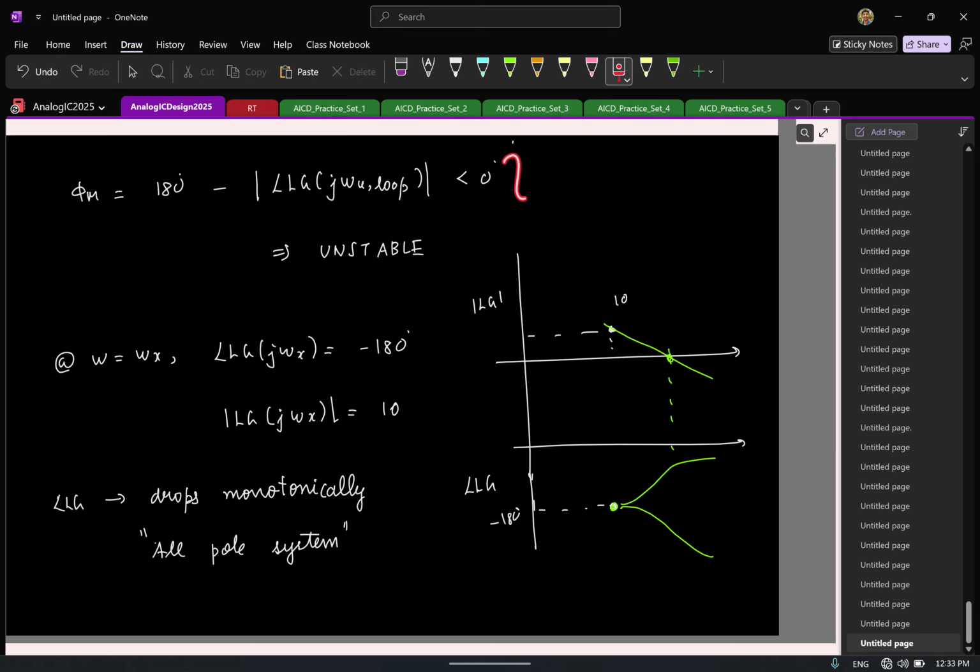So that's why phase margin is a stricter constraint than gain margin, especially if you have LHP zeros. In fact, in practice, there are many systems for which when the phase is minus 180, the gain can be 1000 or 10,000, and still it is stable because of the LHP zeros. All phase lock loops operate that way, and because of that, you can generate clocks and talk on phones. So anyway, this is now said. At least we know that I should look at phase margin, and phase margin must be positive for it to be stable, right?